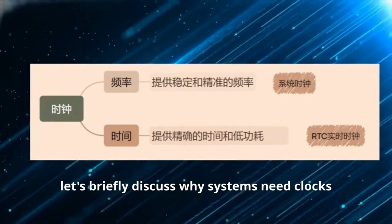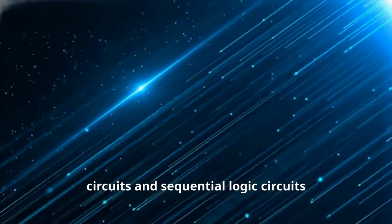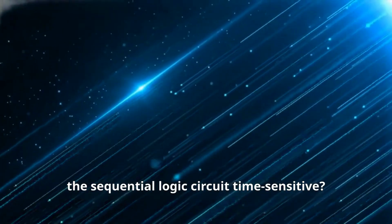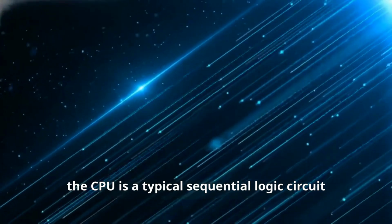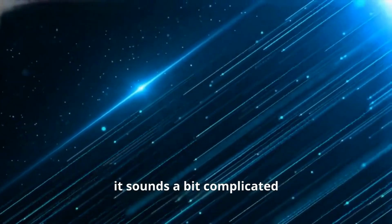First, let's briefly discuss why systems need clocks. Digital circuits are mainly divided into two categories: combinational logic circuits and sequential logic circuits. The key point here is whether it is time-related. In other words, the output signal of a sequential logic circuit is related to the previous state of the circuit. In other words, it is related to time. For example, the CPU is a typical sequential logic circuit, and circuits like this definitely need a clock to operate. Well, it sounds a bit complicated.